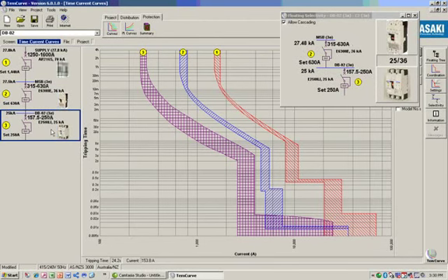And so in this particular case, between these 2 circuit breakers, the E250NJ downstream, which has a fault rating of 25 kA, and the upstream circuit breaker, which is an E630NE, which has a fault rating of 36 kA, we know that we have selectivity to 25 kA and cascading to 36 kA between these particular breakers from our test results.